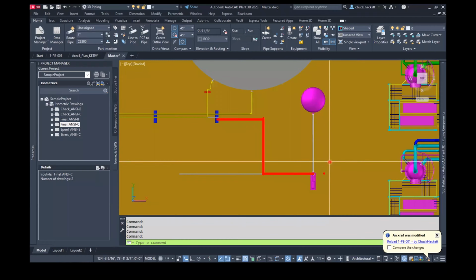By the way, we got an update from our customer. They want to go ahead and put in a backup pump in this area here. Okay, they want it to be just like this one. And don't forget to put in your valves on this guy, and we'll need a clean out or a drain and another valve here.